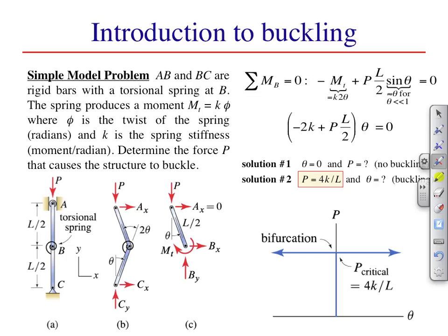The actual treatment of buckling must be examined in the context of a deformable body. As that is beyond the scope of this class, we replace a real vertical column with a contrived assembly: 2 rigid bodies connected by a torsional spring. Here, all the flexibility of what is normally a continuously deformable body is lumped into the spring. This model won't provide the right scaling, but it gives us some insight into the bifurcated nature of buckling.